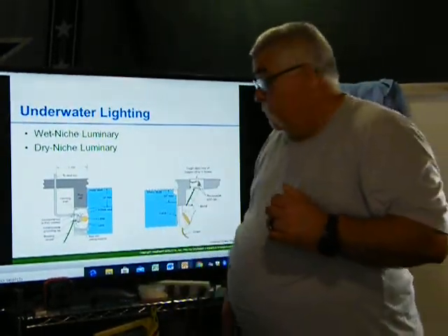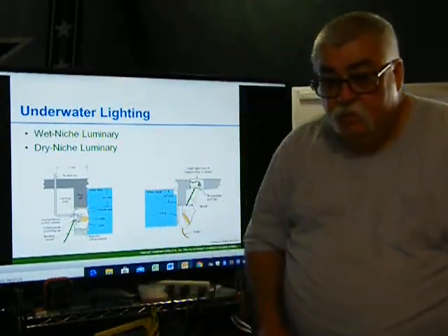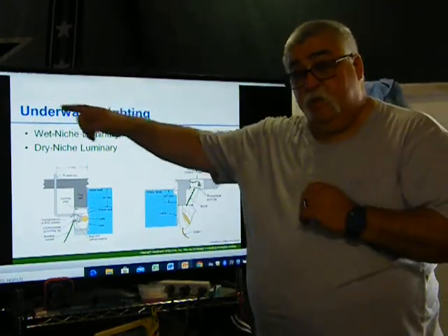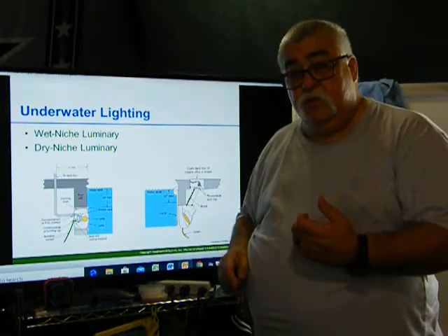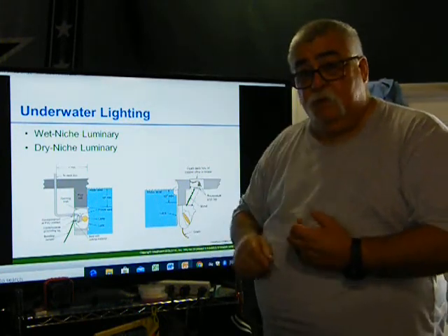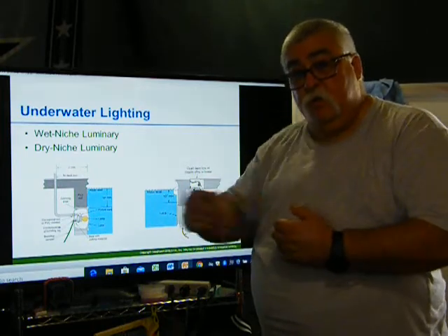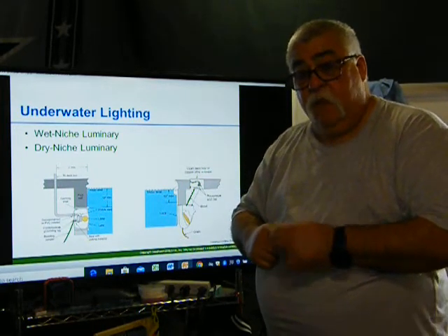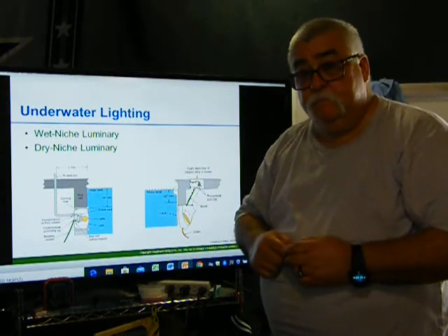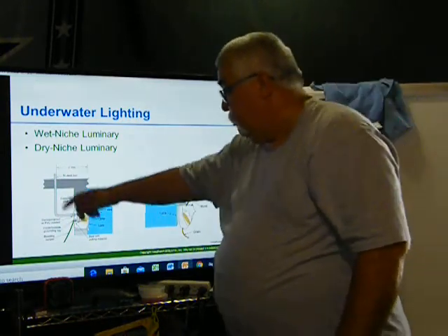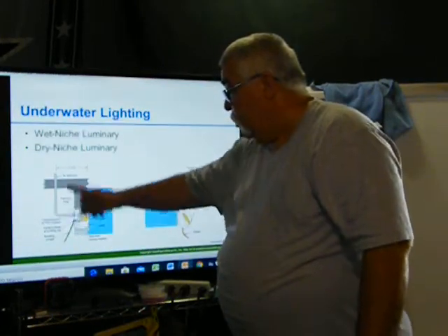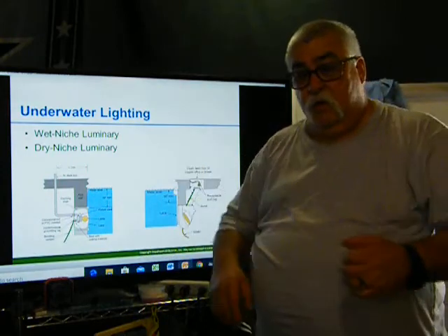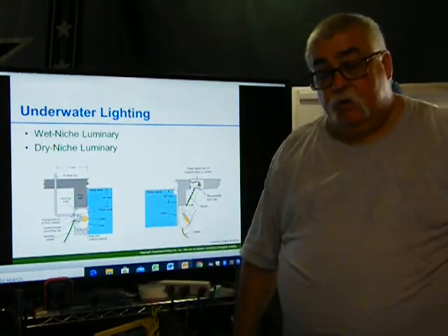We used to use 12 gauge because we used brass, and we brought brass from the source. When we came into whatever box we were doing, we put a grounding bushing. We ran brass up, put a grounding bushing, and bonded that conduit, and then we ran number 12s. So we had number 12 coming in, and then we had number 8 going up to our boxes. Instead of having 2 conduits, we had one. Off that one conduit, we bring over the number 6.